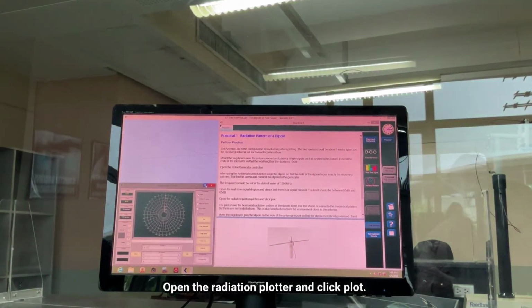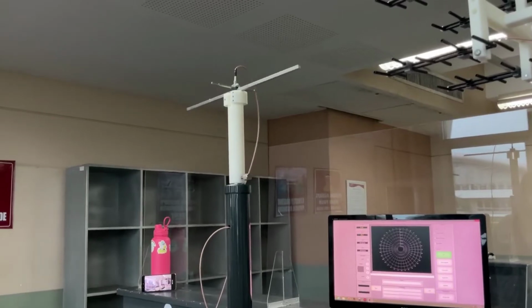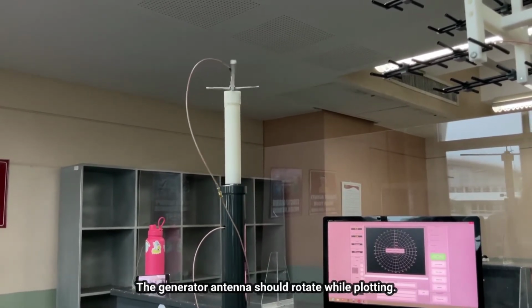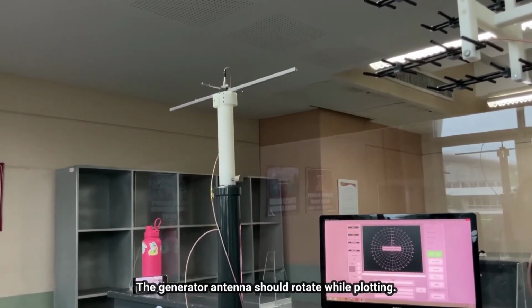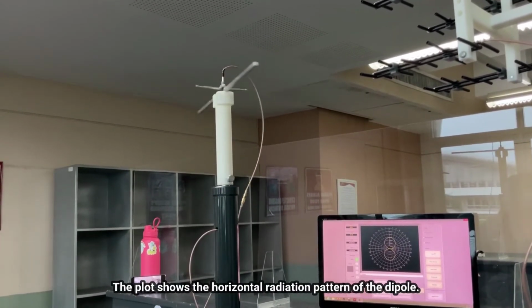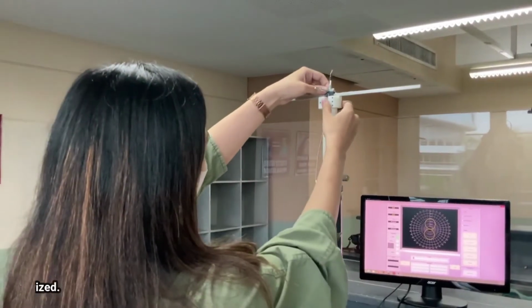After that, open the radiation plotter and click Plot. The generator antenna should rotate while plotting. The plot shows the horizontal radiation pattern of the dipole.